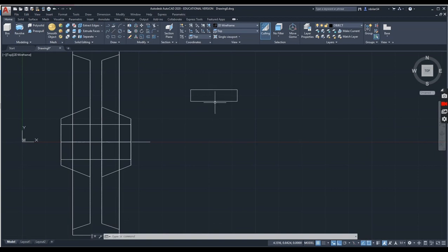I now need to put a center line. That's going to be 1 1/4 down from here. That's where we're going to rotate these around. So I'm going to draw a line from the midpoint, and I'm going to go down 1.25, and then I'm going to go out, maybe I'll make it right even with this one.